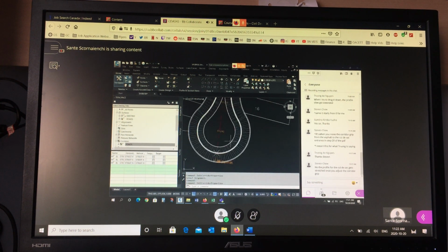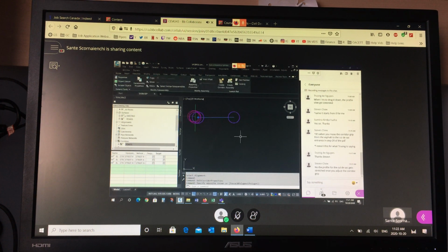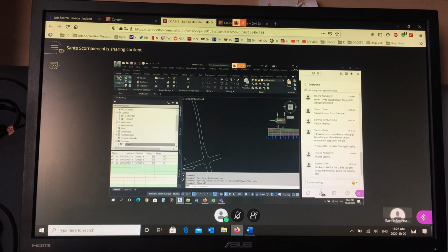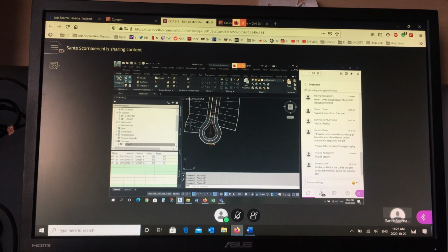Is we want to take this piece, the pavement. Let's go back to the cross section. I want to take the pavement piece and use that targeting function to make it longer. I want to extend these all to the center line horizontally, and vertically I want it to match the elevation of the center line. Okay, so that's a targeting issue. Okay, so we do that again here, and I'll show you. I'm not going to show you in 3D. I'll just show you on the